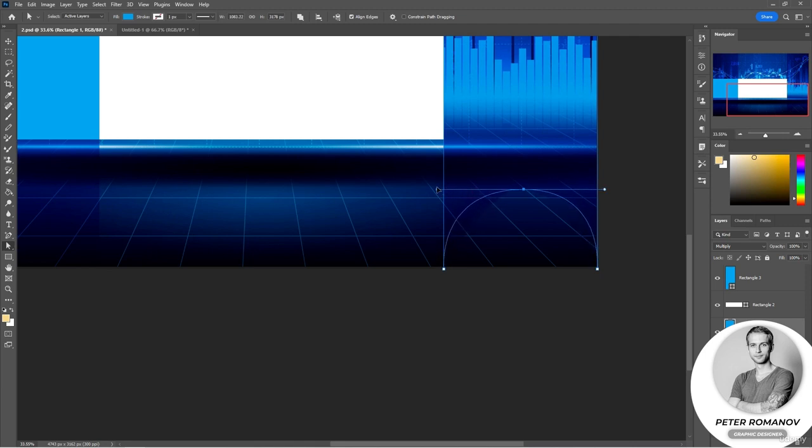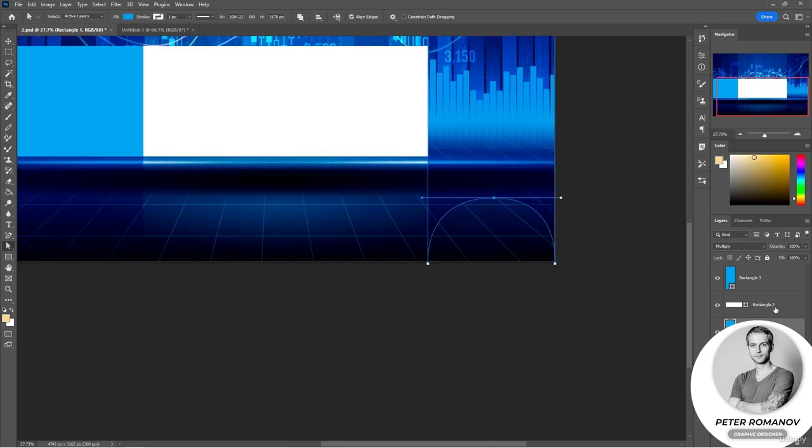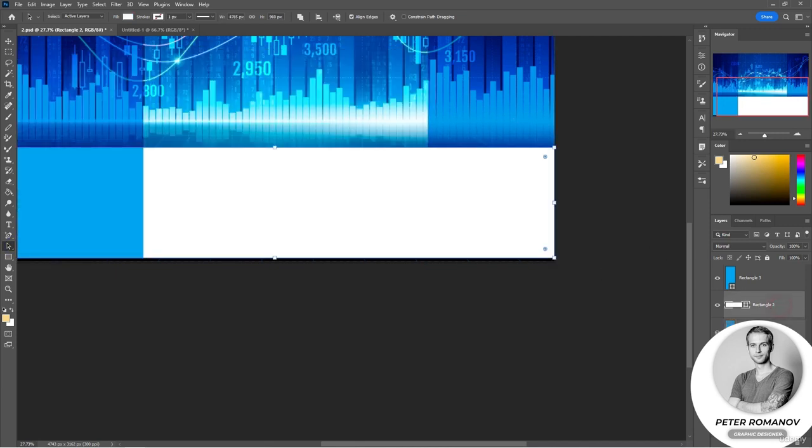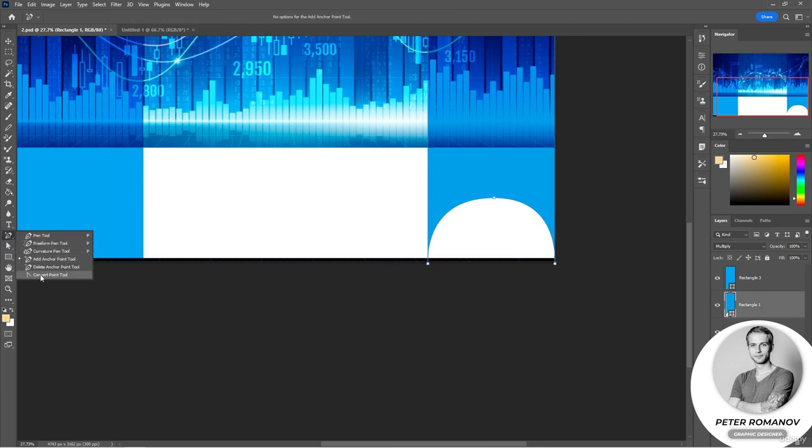I take this line, move it here, and the path becomes like this. It could be done, for example, like this. I can twist it. As you see, it fit. An additional point automatically takes exactly this form, but sometimes we need to create a sharp angle. In this case, we go to the pen group tools, and at the very bottom we have the convert point